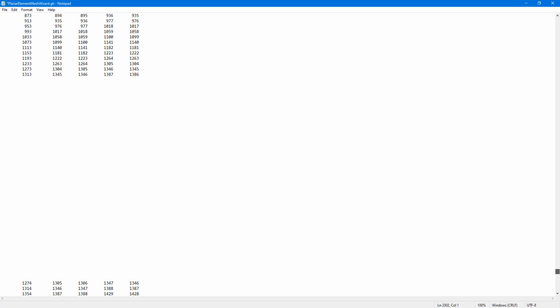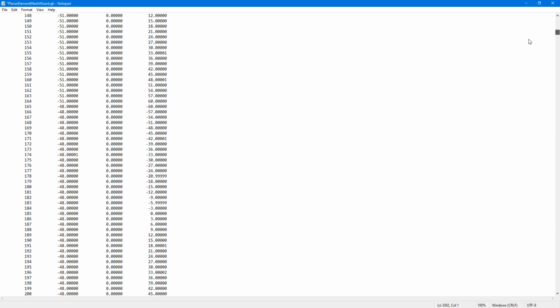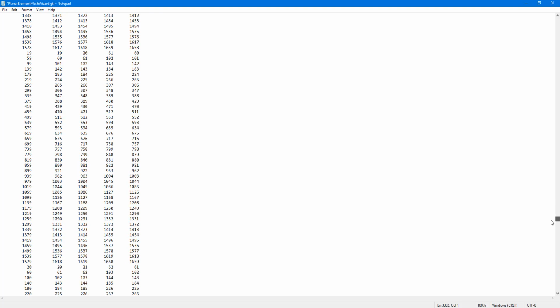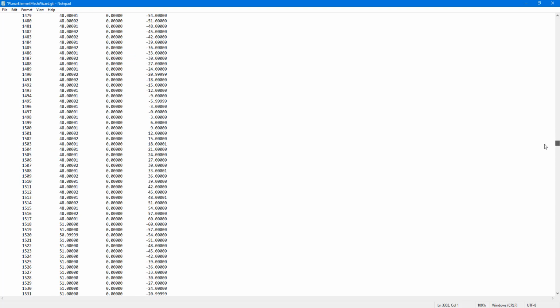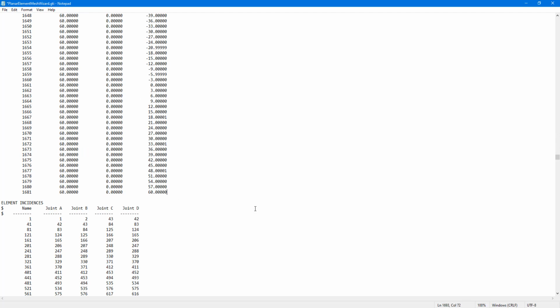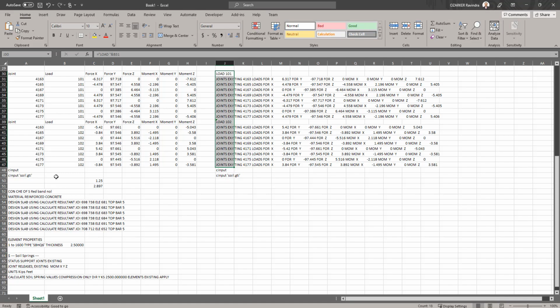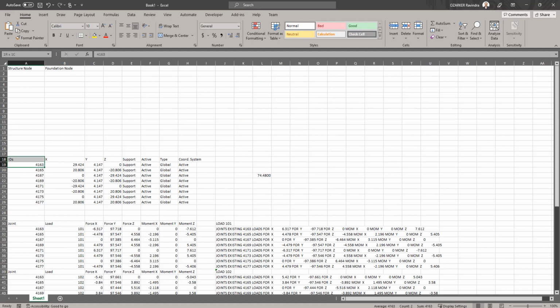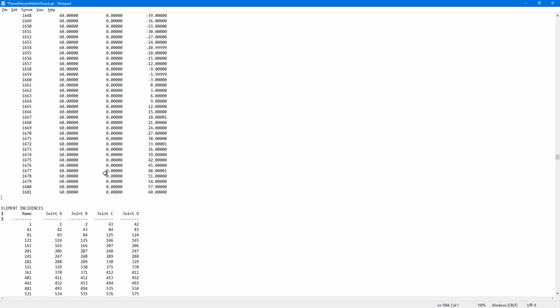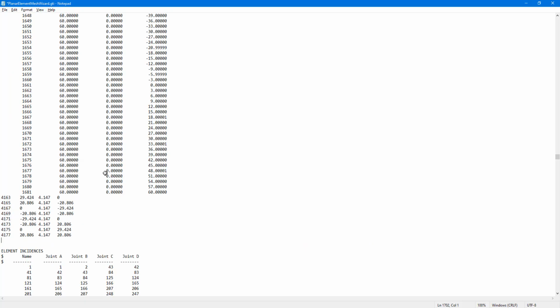Also, the structural engineer has given us the location of the tank base plates, XYZ coordinates of that. So what we can do is we can come down to the end of the node coordinates, and we can go back to our Excel file that we had. In this Excel file, you see all these IDs, XYZ coordinates, you press Control C and Control V. Now you can also do that using the graphics or the data sheets. I'm just showing you another way, okay?